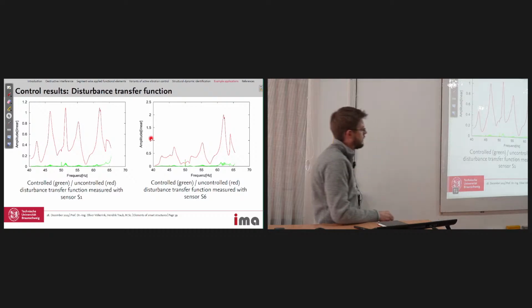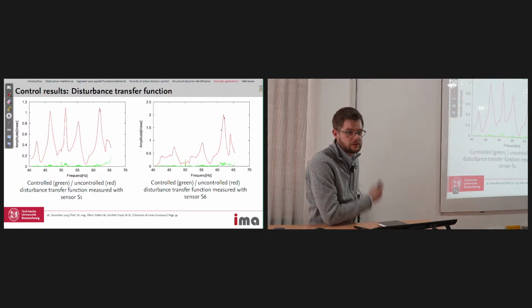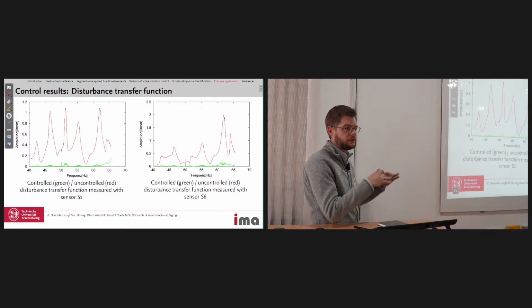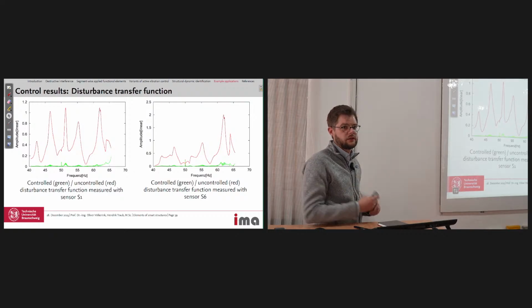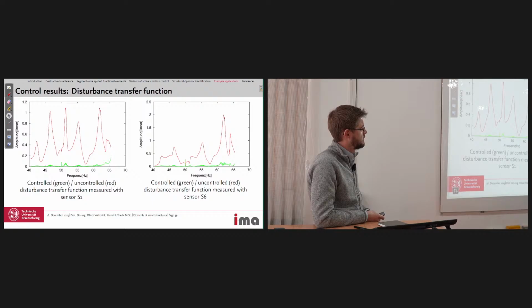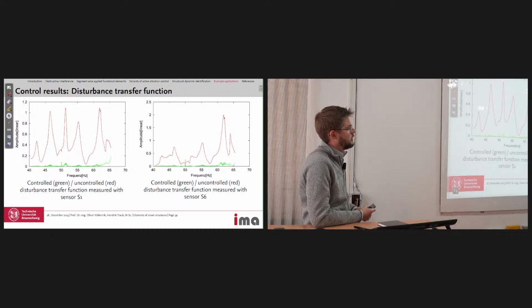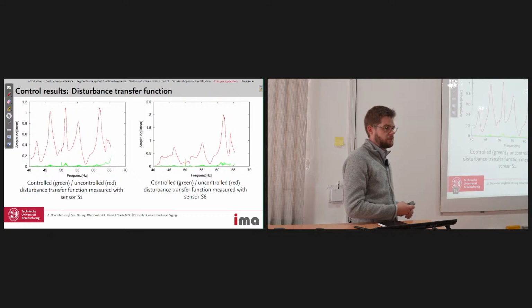Yeah, and I think in real structures, the influence of the higher eigenfrequencies decays. So maybe you have to look at the first 10 eigenmodes to completely or nearly suppress all vibration. Yeah, I mean, you can perform finite element based modal analysis.